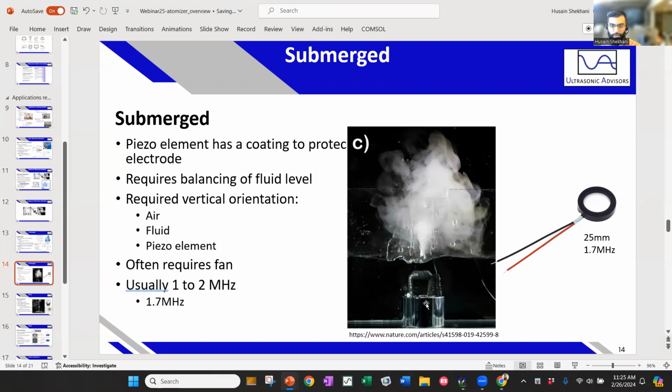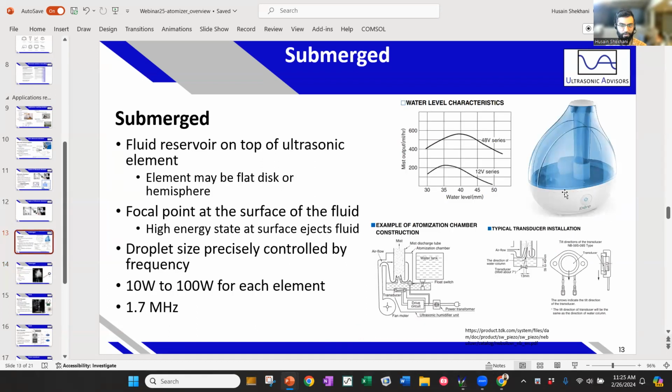And this is an ultrasonic fogger. What's sold is a kind of fogger, in a vat of water. And as I just described, if the fluid level increases or decreases, then there's going to be a change in performance. So it has an additional constraint that you have to control mechanically: the fluid level, which your home humidifier does. It has valves and a water float, which controls the fluid and whether the device can turn on or not.